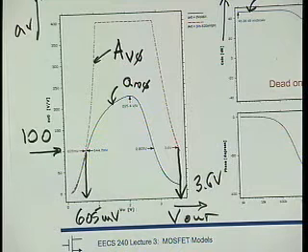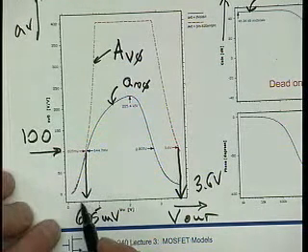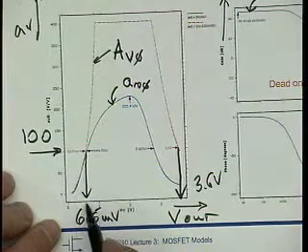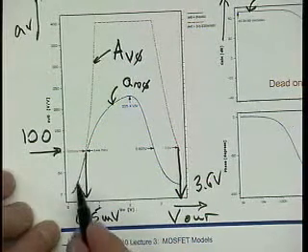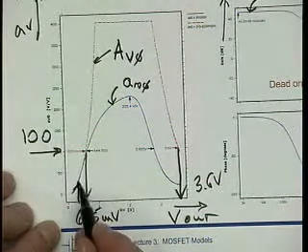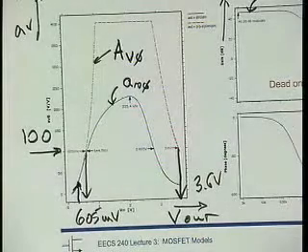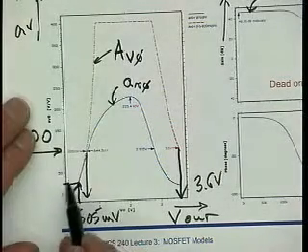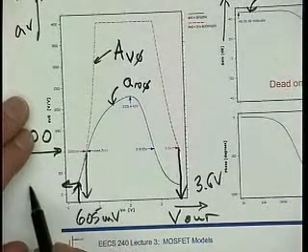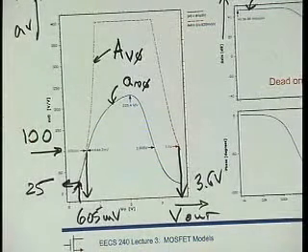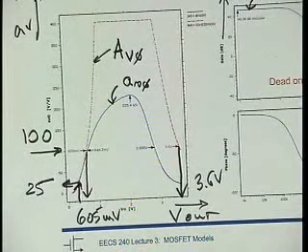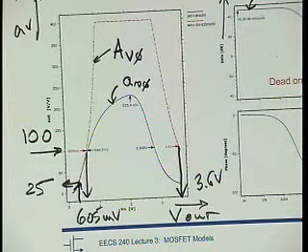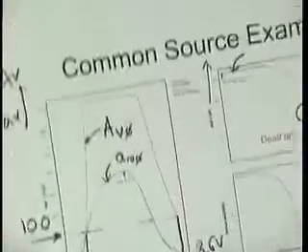If we wanted only, maybe, 300 some millivolts or so across our transistor, which is still larger than V star, right? Then the gain would drop down to something like 25. Okay. It really depends, right? We can get a lot of gain, but we need a lot of voltage. It's very expensive. We don't have a lot of voltage.